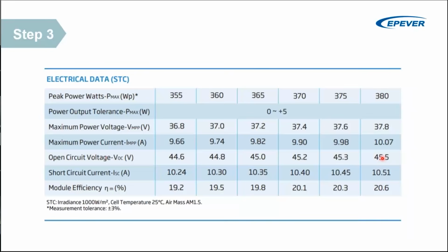It's not a fixed voltage either, and normally it's not mentioned in the PV specification sheet, so don't look for nominal voltage for solar panels in the datasheet of the panel that you want to purchase. It's a number that we associate to solar panels to ease the designing process. The number of cells and the VOC can tell a little bit about the nominal voltage. For example, a nominal 12-volt solar panel has maybe a VOC of about 22 volts and a VMP of about 17 volts. But for sure, I know that the panel that I'm choosing is 24 volts. If you are not aware of the nominal voltage, it's better that you ask.